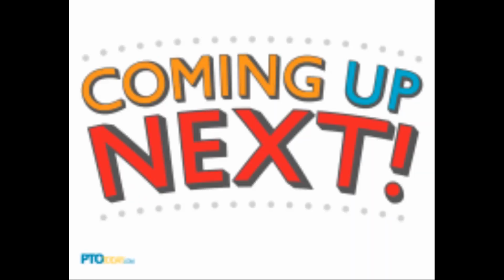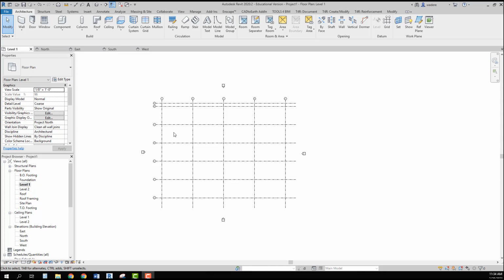In this video, we are going to continue with our architectural plan by first setting up our precast wall types. As I mentioned in the other video, we are going to keep our precast wall pretty simple as far as precast wall design goes. So the first thing we want to do is make sure that we create our walls under structural instead of architectural, even though this is an architectural plan, because we are actually going to bring our architectural plan in and use it as a structural plan.